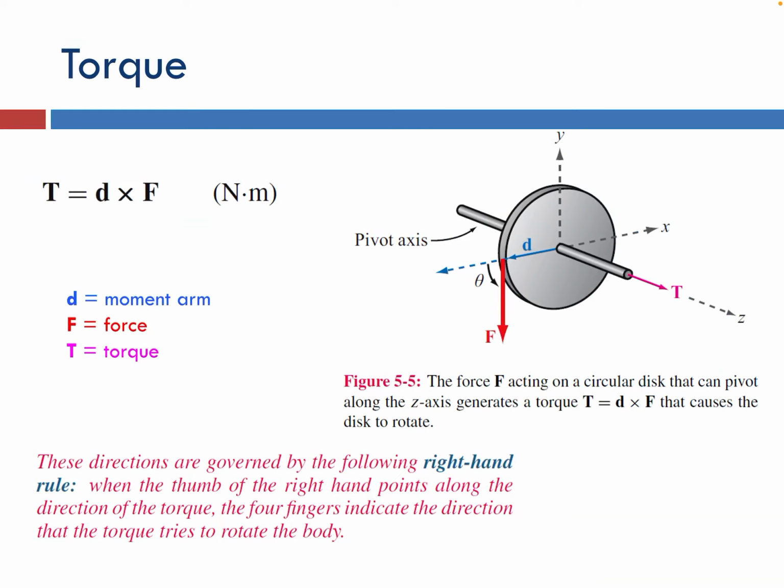Okay, and the other important, maybe mechanical concept that we'll talk about related to magnetostatics and that will apply to generators is the idea of torque. So if a force acts on an object that is fixed but able to rotate about an axis, this quantity torque, that is the arm of the force times the force, gives us the torque, which is a measure of rotation and the magnitude and direction.